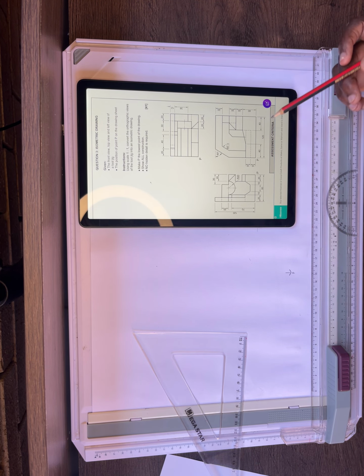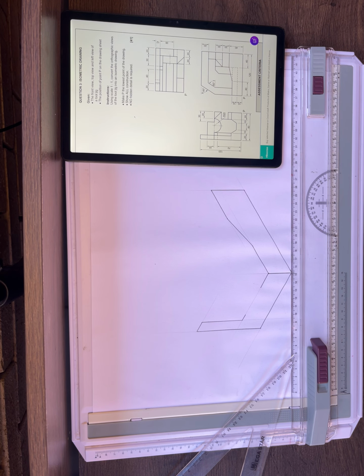And you know that for us to draw polygons, we have to start by constructing them before we project them here, since the polygons are not making isometric lines. But for this one, we are given all the details. We have got 15 going down, and then also they're giving us these spaces here, that is 10, 10. So we are going to measure 10 here on this side.